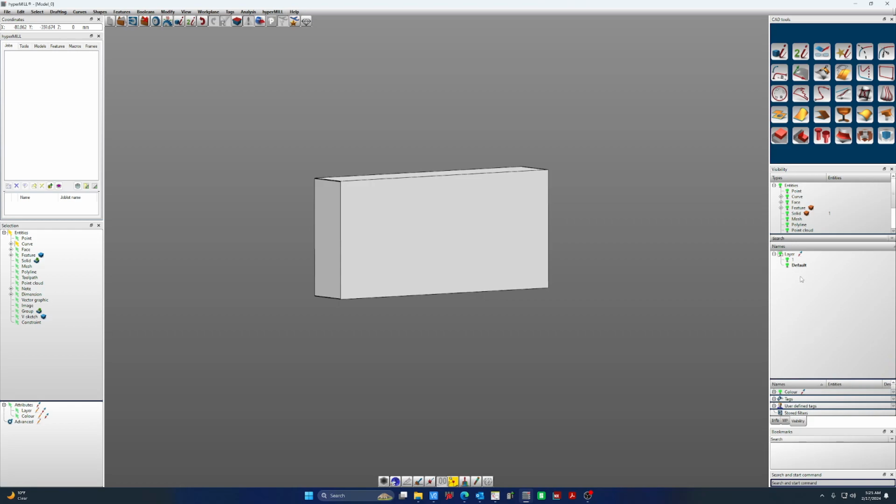If you like to have a really organized CAM workspace as it relates to all your drive geometry, surfaces, and work holding solid body, then you're going to want to really leverage the layer functions over here. As we get a little further down, I'll jump into some of the templates that I use. You can have containers inside containers, and I break down different operations. I put all my work holding together, I put all my geometry together, and I put surfaces together so I can quickly switch between different operations.